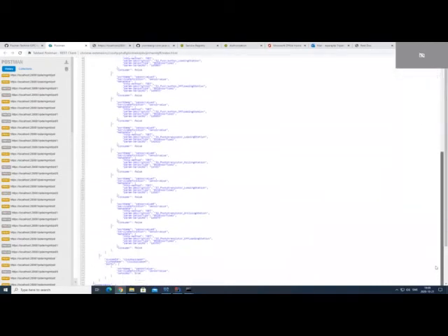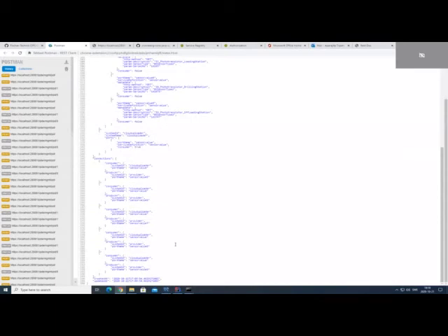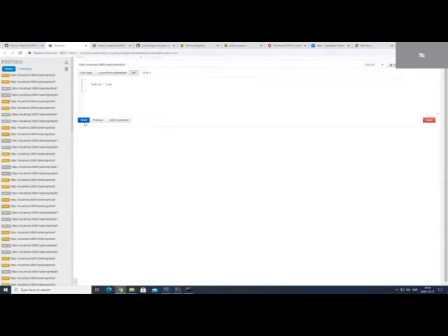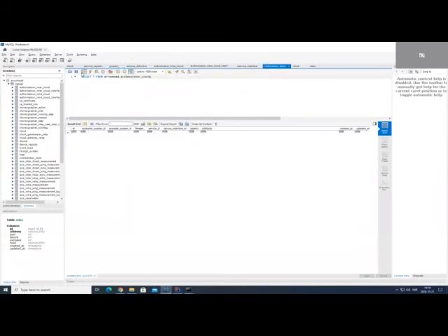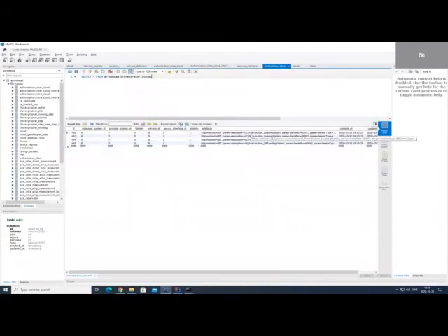So the first entry I showed is allowing the Cloud Uploader to avail the first 4 sensor value service instances for getting the status of sensors I1 to I4. And the second entry is creating the rules which will allow the Cloud Uploader to access the last 5 service instances of sensor value for getting the status of sensors I5 till I9. So now let me activate one of the rules. So I have activated it now. If we check the store rules, we will see rules getting created for accessing service from I1 to I4.